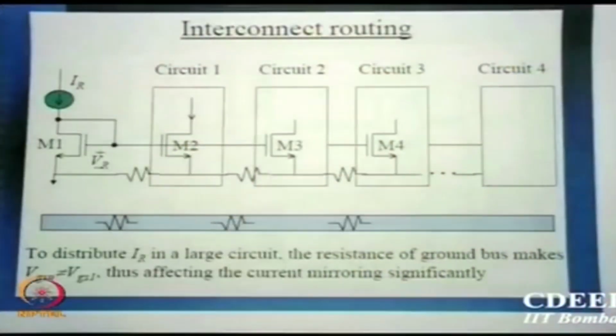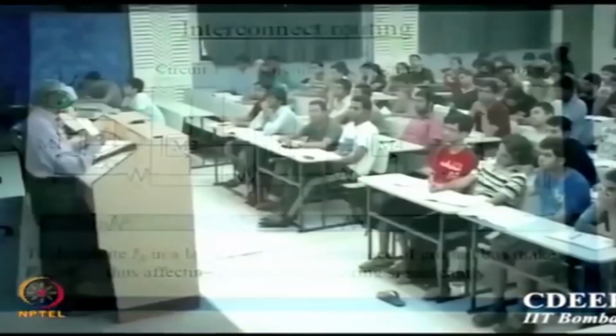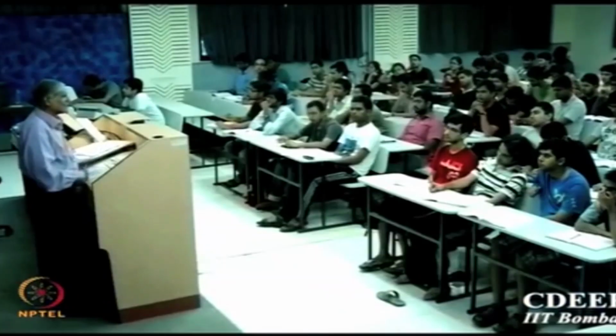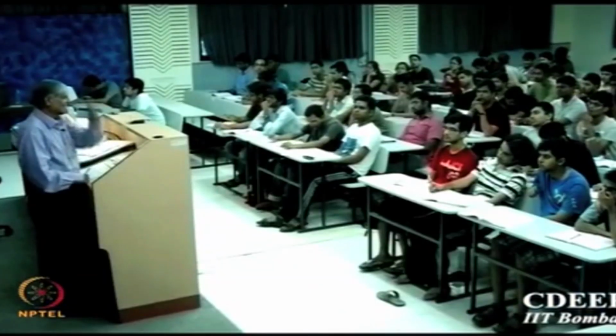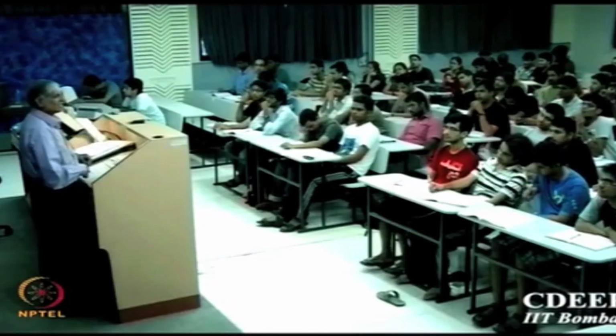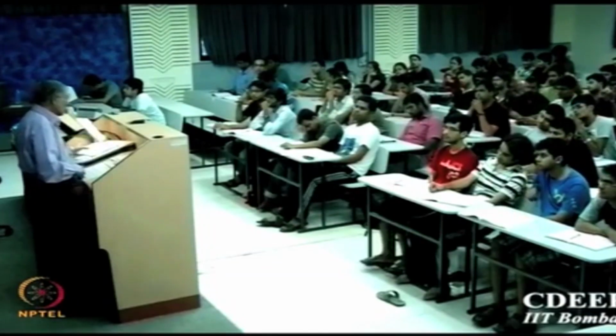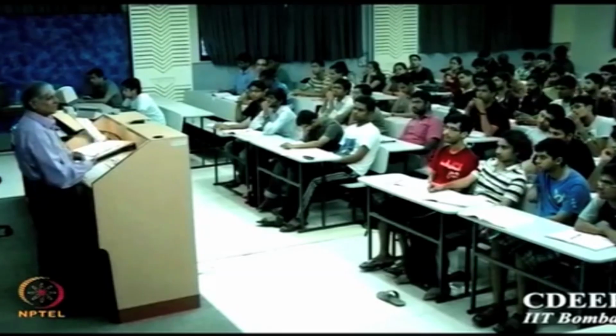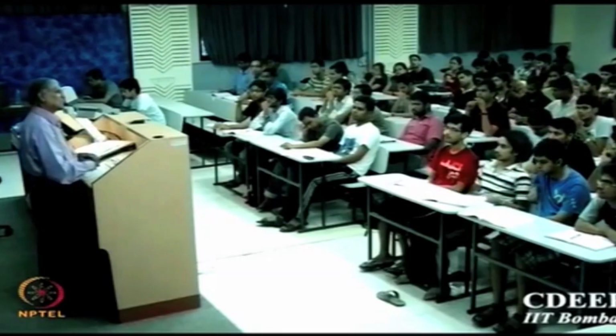Also, now I will say you don't use single references. Even if it doesn't matter as far as circuit things, run another circuit ahead, another mirror, and run ahead. So break into a number of references in case you feel too many such things are running from one point. So don't run from one point. This is also done in digital: keep buffering or actually putting VDD lines at 4 places.